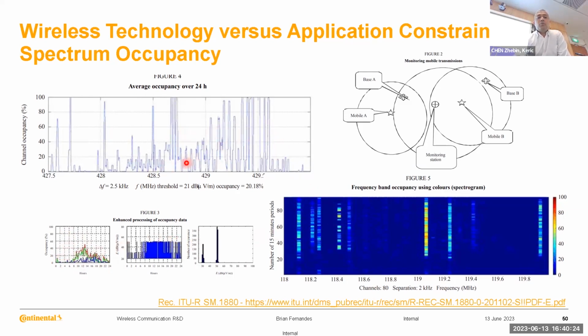So you also want to be able to use areas of the spectrum that are not heavily utilized, so that you have the availability of your feature all the time. So the robustness, the reliability increases. Because if there's a lot of other communication occurring in your spectrum, then your signal could be lost, there could be collisions, there could be too much interference, and therefore a small signal to noise ratio. This could affect the function as well.